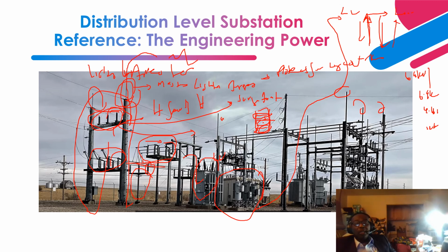If you don't implement a means of regulating that voltage, then you're going to have a power quality problem. So we have voltage regulators connected in each phase, phase A, phase B, phase C, on the low voltage side, feeding the customer, to regulate the voltage on the low side. This one is a typical vacuum circuit breaker on the low voltage side that feeds the customer.